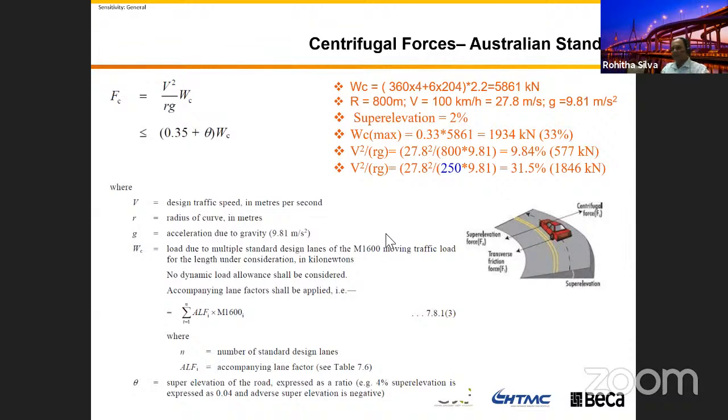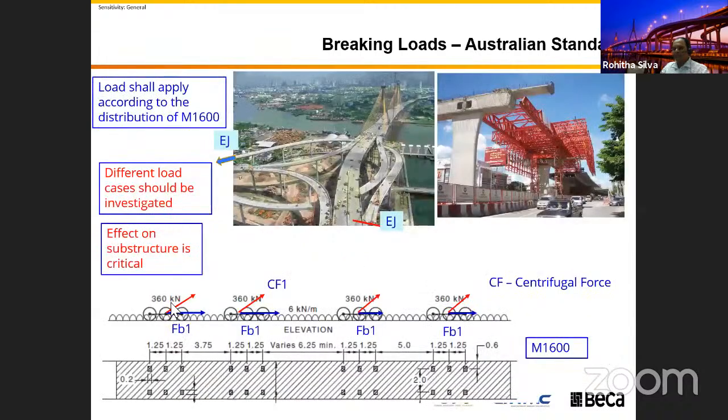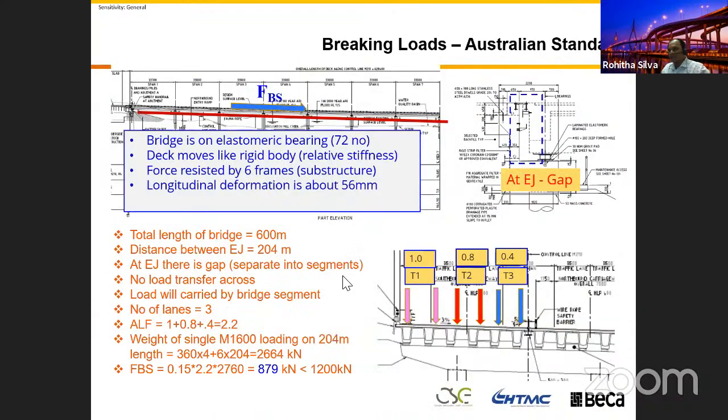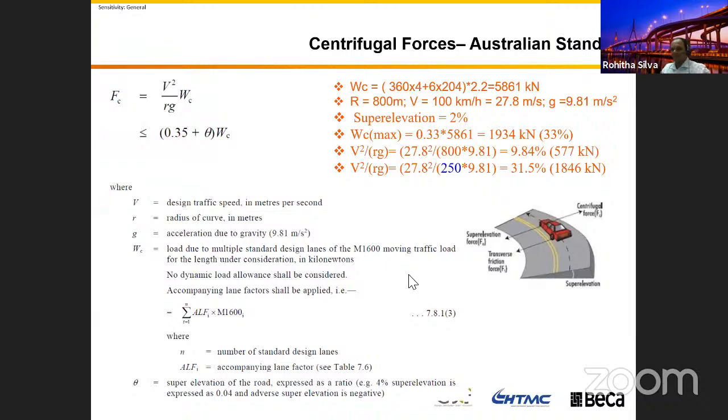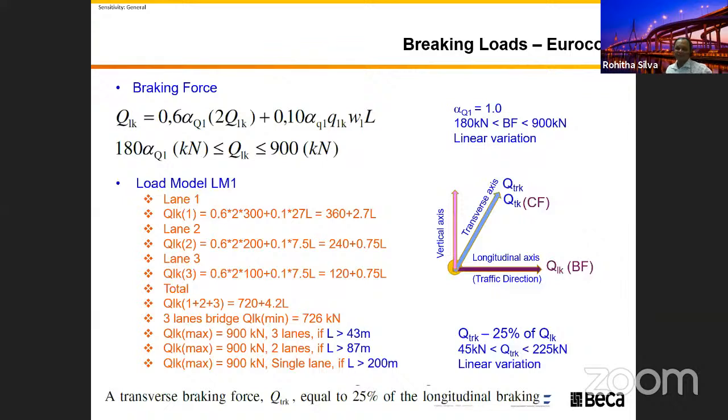Similar to the braking load, you can apply your braking force as one load, or, if you want a more accurate analysis or design check, you can apply it at your axle locations. But I recommend applying one braking load and one centrifugal force together. They are perpendicular, one in the longitudinal and the other in the transverse direction. Similarly, Eurocode defines the braking loads